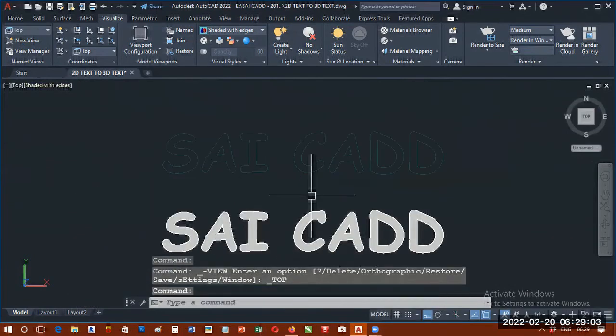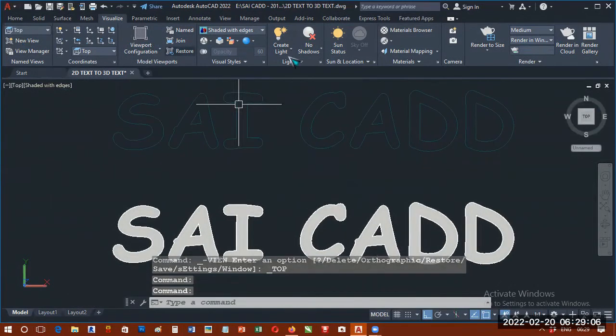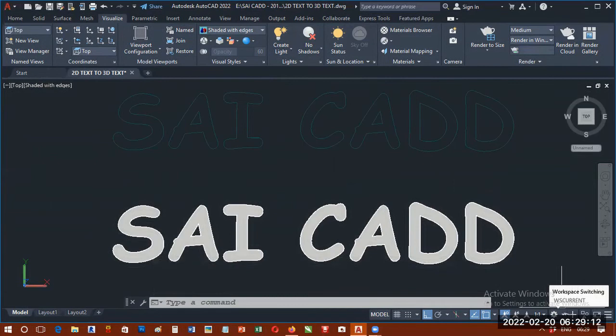Okay, now I want to reset my 3D panel to the 2D panel. Again, you go back to the same process. Come back to the bottom right of the screen, click on workspace switching and choose drafting and annotation. This will bring back the screen details to top view.